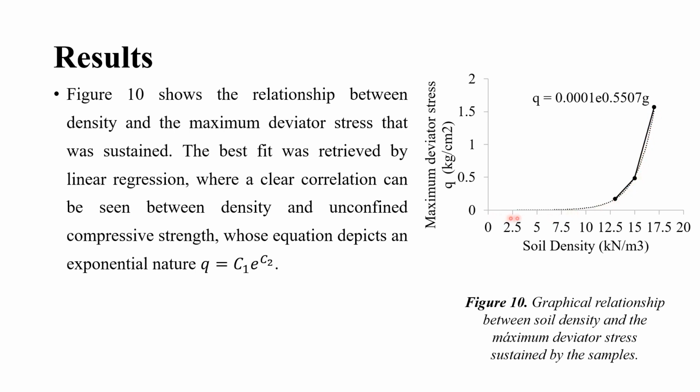We can see that there is a clear form of equation represented here for the particular soil that we have used, where the maximum deviator stress, which is the maximum compressive stress on simple stress conditions, is represented better by a non-linear relationship.